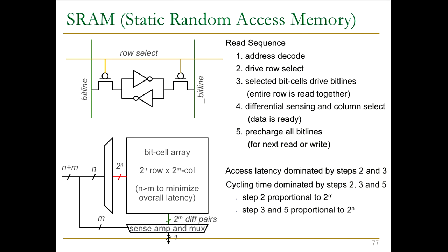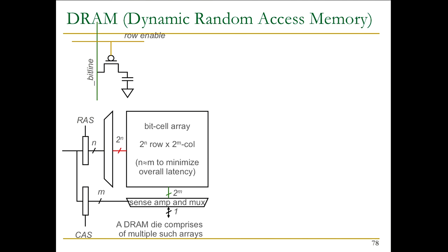SRAM is fast, and also it's on chip, usually. So you can supply the address bits for both the row and the column at the same time. Whereas DRAM is almost always in a separate chip. That's why we have latches over here. Basically, you supply the row address first, you latch it, you access the row, and then you supply the column address next.